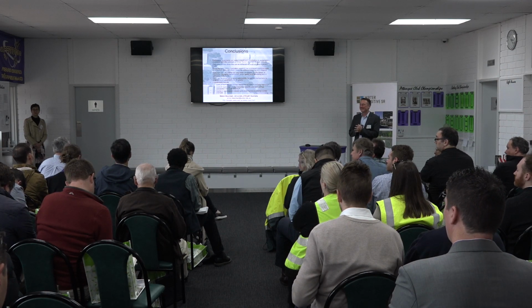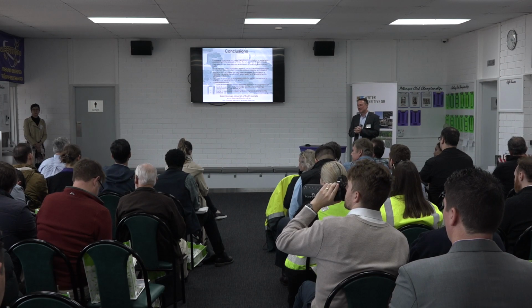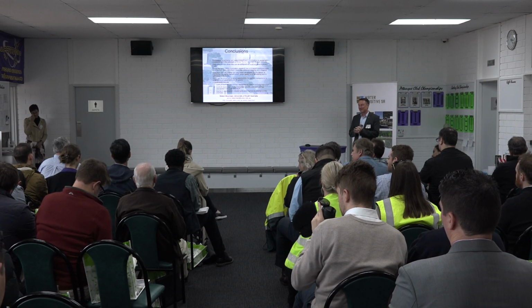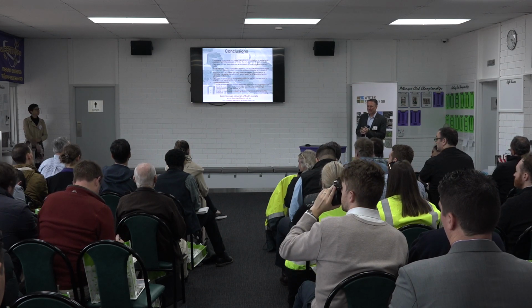For a lot of the stormwater hydrological designs, we use DRAINS. I think you mentioned DesignPave as well. Is there a way to account for this accurately in DRAINS? Yeah, no. DRAINS is written by Jeff O'Loughlin. I used to work with Jeff in Sydney. It's an excellent stormwater program, but at least last time I looked at it, it was not designed for permeable paving. So there's no easy way of modelling it.